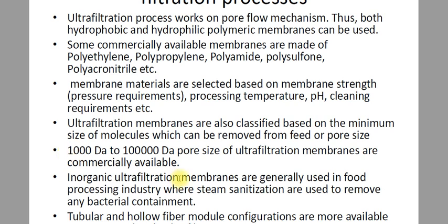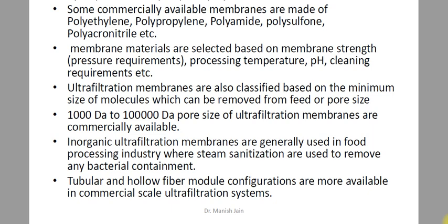Now inorganic ultrafiltration membranes are generally used in the food processing industry. Why are inorganic membranes very useful for the food processing industry? Because suppose you are using the ultrafiltration membrane for concentration of whey protein, then you have to sanitize the membrane. Steam sanitization is very much required. Why? Because otherwise bacteria will start to grow inside the membrane, since you are using it for food processing.